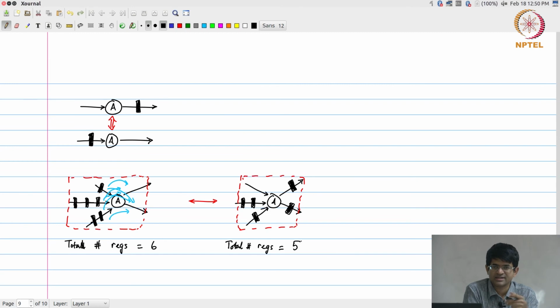Under those constraints, it is possible to set up complete optimizations. You could either try to optimize the critical path and therefore the speed at which the system operates, or you can try and optimize the total number of registers present in the circuit, which in turn is related to the area occupied by the circuit, or in some cases you might even have some other combination of these, right, some other metric that you are interested in, which is the sort of balancing, where are you able to place the registers, in which part of the circuit do the registers go, and how are you able to use them.